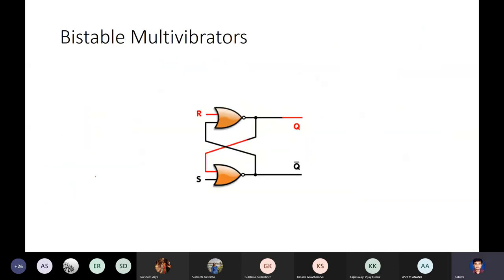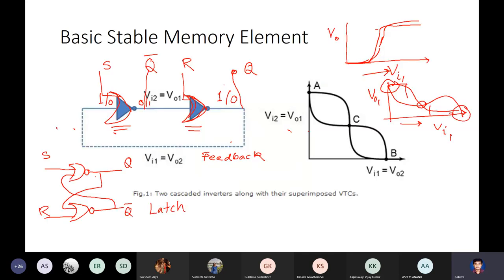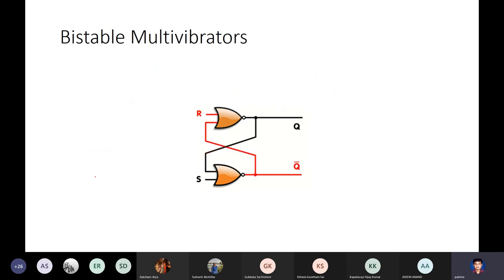So you can also easily see that. I have a kind of a small animation. You can see, if R is set to 1, this is becoming rather an uncontrolled sequential action that's going on, but I cannot control it anyway. So when R is set to 1, you will see that whatever is the value of the other input, it's a NOR gate. So when R is 1, the output is anyway 0. So this becomes 0, irrespective of what this other input is.